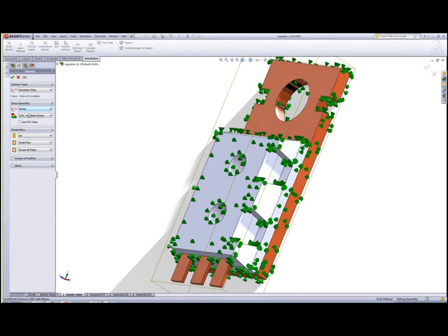I want to go in, stress is fine. I want to choose my step criterion here. I can select actually three different options. I can select across all steps. This tracks the simulation data value across all steps for the entire model for the selected entities and reports it as a single value. Also, I can do a specific plot.